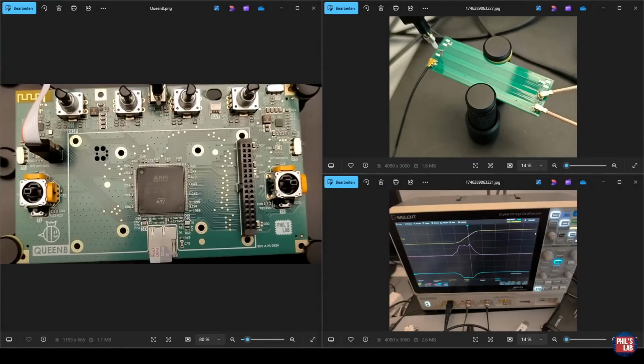In this video, I'd like to discuss the basics of crosstalk as it applies to PCB and hardware design, go through some real-world measurements of crosstalk, and then also discuss how you can reduce and hopefully mitigate crosstalk to a certain extent in your own PCB and hardware designs. This will go through some practical tips, looking at actual implementations in terms of your stack-up, geometries, trace spacing, feature spacing, rise times, and much, much more.